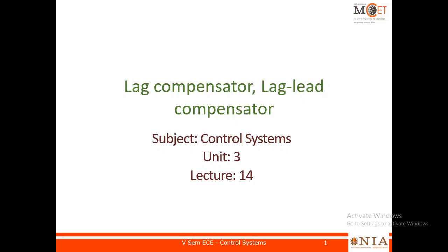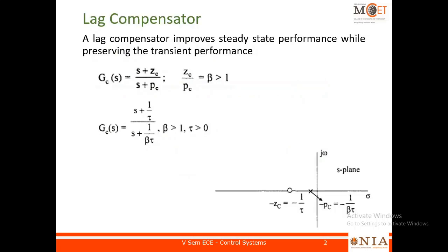Students, in this video, we are going to look at lag compensator and lag lead compensator. So, first point in lag compensator is it is something which is complementary to the lead compensator. The lag compensator will improve the steady state performance of the system while not disturbing the transient performance. Okay, so it is meant for improving the steady state performance.